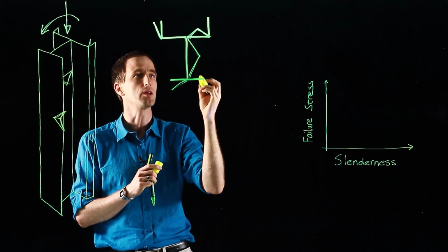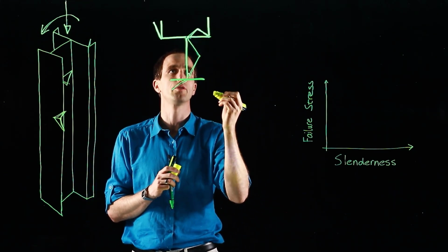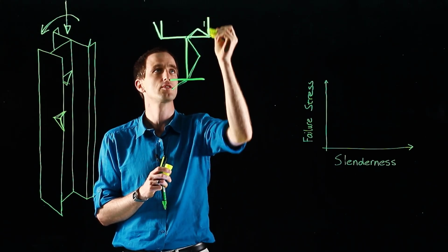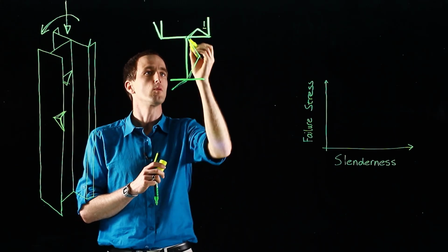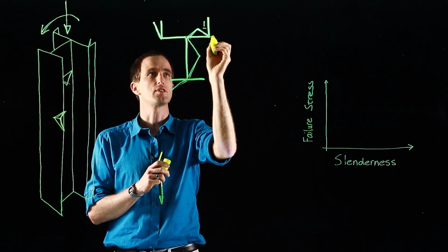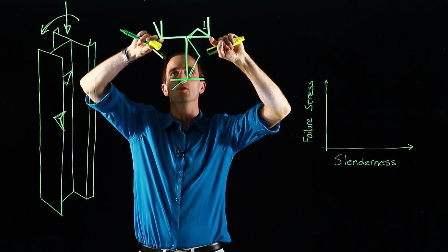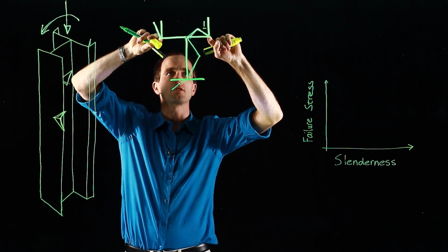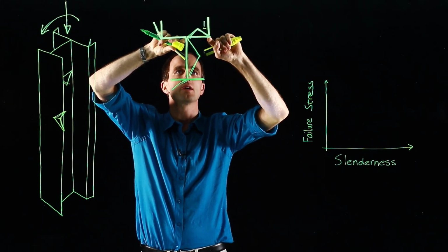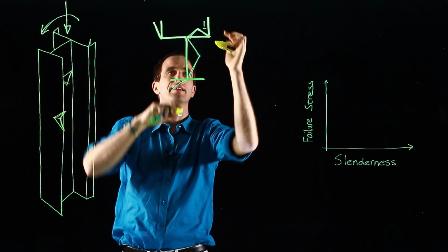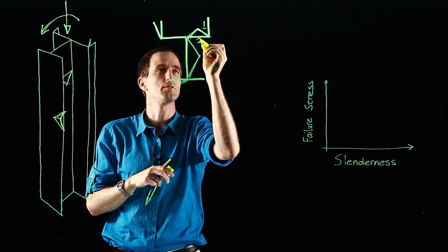So for our section, we would need to classify all these different sections. For instance, this top flange, each side, is supported along one edge. Whereas this horizontal section, if it was a channel on its own, that would be the length we classify. But now we've welded something into the side, so when it buckles, it's only this length and it's two edges, so it's two edges.